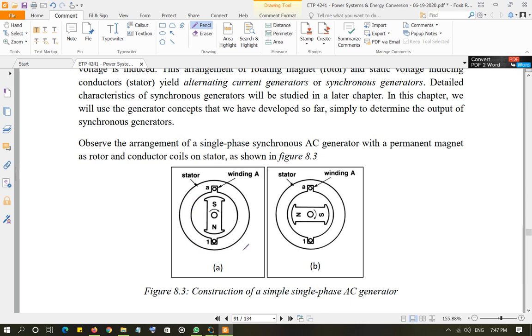Here in most of the AC generators, especially the ones that produce high power, high current, high voltage, you don't put a moving armature. Why? Because of course in the moving armature you have to put brushes, and then when the high voltage, high current is coming out, there will be a drop at the brushes, and you will lose power. The brush life is going to be less, and you don't want the high voltage, high current part to be moving.